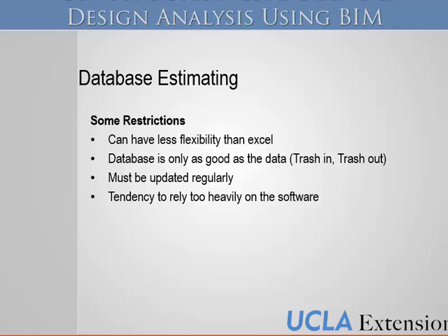And then you have your construction contingency, and that's for more things that you just didn't see. Things got detailed a little better, and this actually needs to be gold plated instead of just stainless, or things like that. So contingencies, that's how you account for that. You try and do your best at thinking about every possible thing that could be needed on this one napkin sketch, and make assumptions, and then you throw contingencies at it.